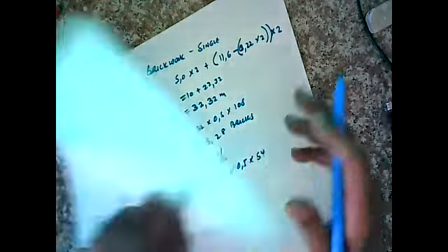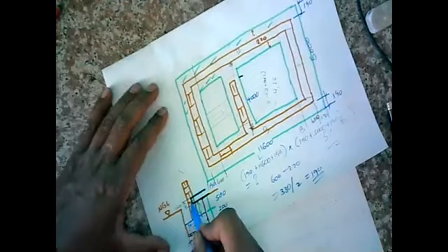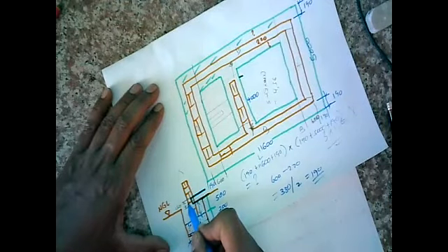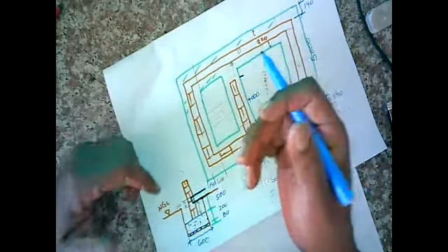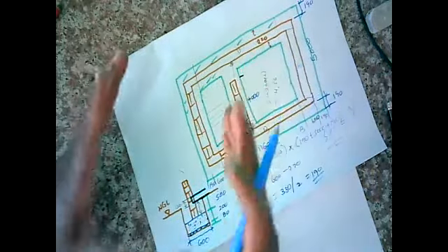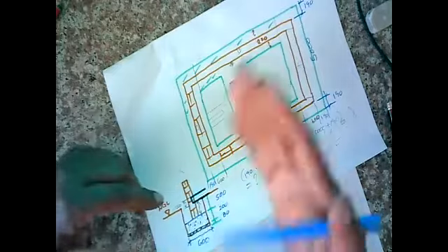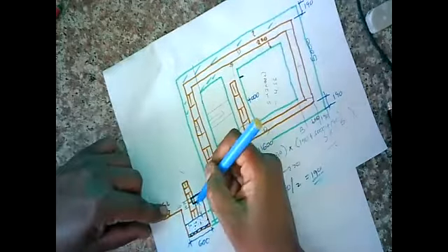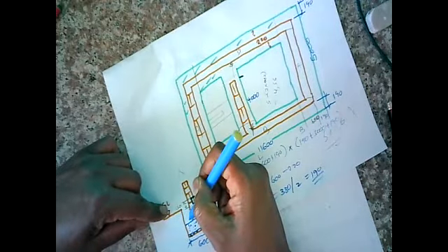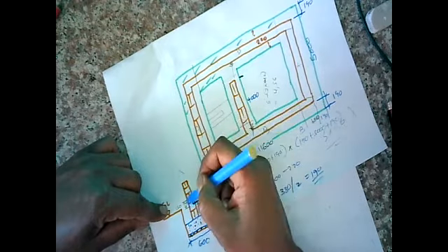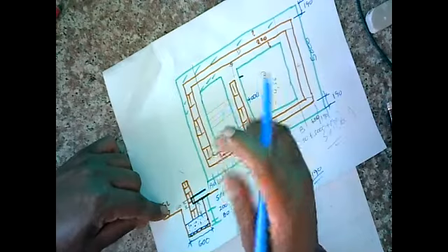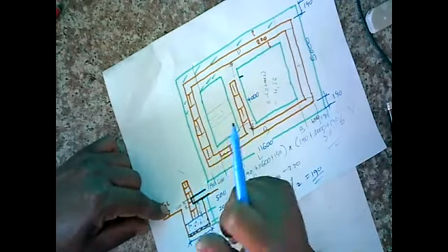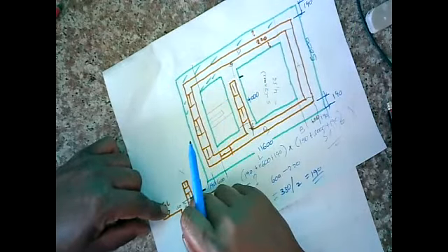Now let's look at brickwork around it, around the slab. Right, now you're going to ask yourself why we do this, because we're basically using brickwork around the slab as some sort of formwork, because when we pour the concrete, it doesn't spill over. All right, as opposed to putting formwork there to hold it up and all of that. So in the building process, we actually cheat, right? But it's accepted building process.